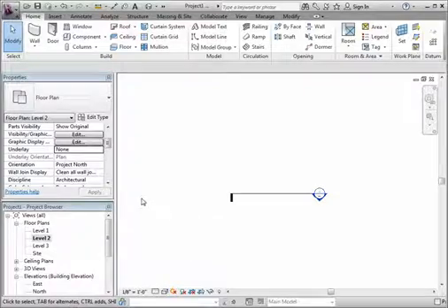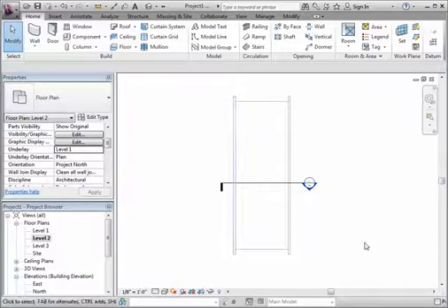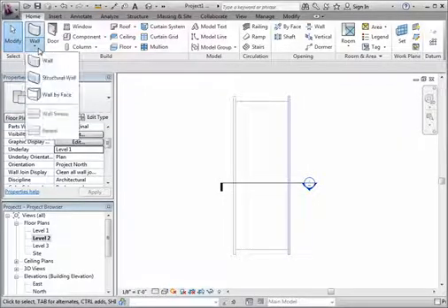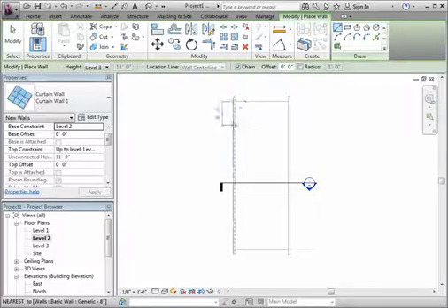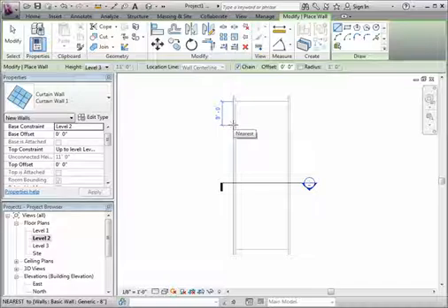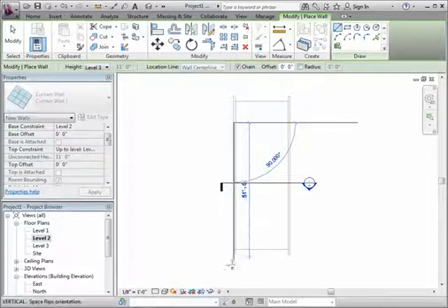But in this case, I actually want to use that floor plan to draw over. So I'm going to use that as an underlay, and then I'm going to draw 2 more walls. I'm going to pull them 10 feet off the edge. So if that's 2, that makes that 8. It wants to be 8. And then I'm going to make this.